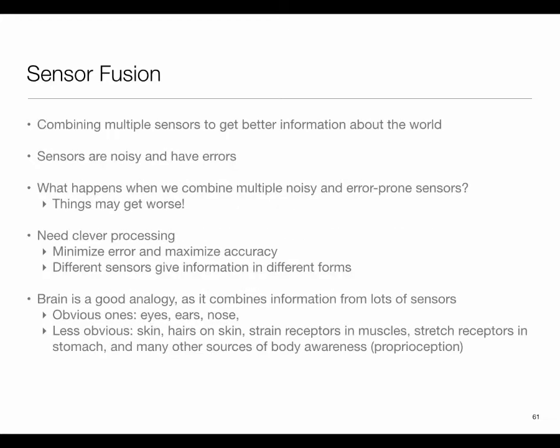And the final part, which we often do, is sensor fusion, which basically says instead of depending upon only one sensor, you now begin to combine readings from multiple sensors. One reason you do it is to make things more robust, and the other reason is oftentimes one sensor may not have the complete view.